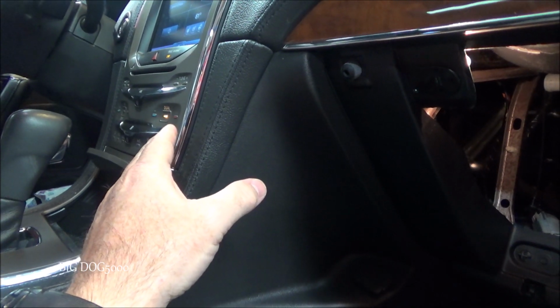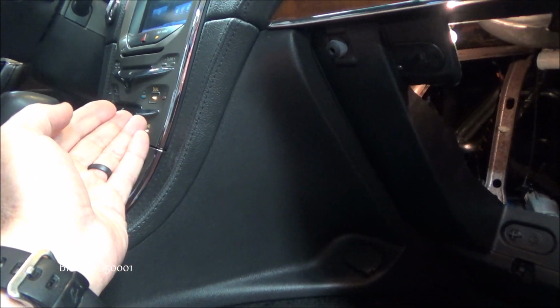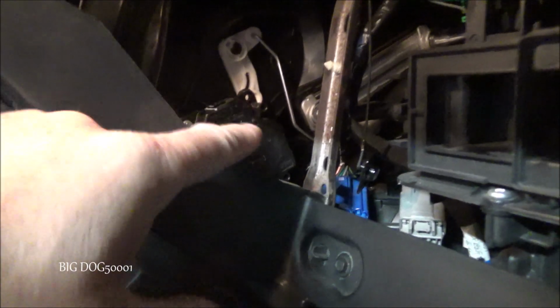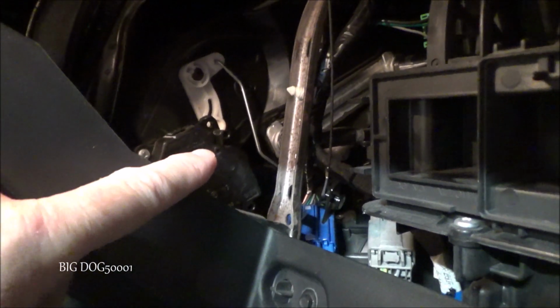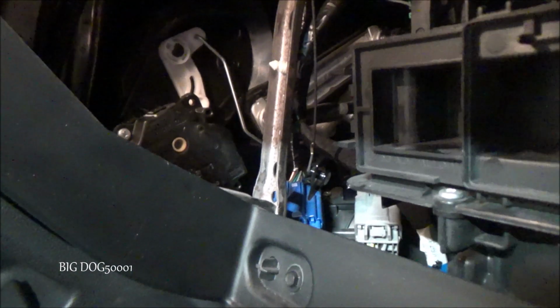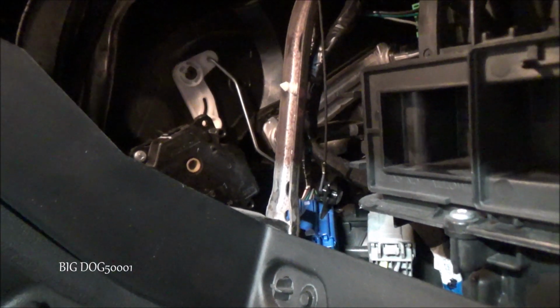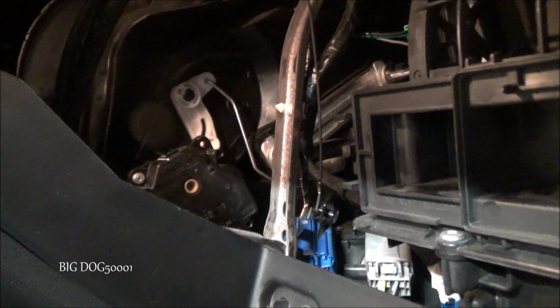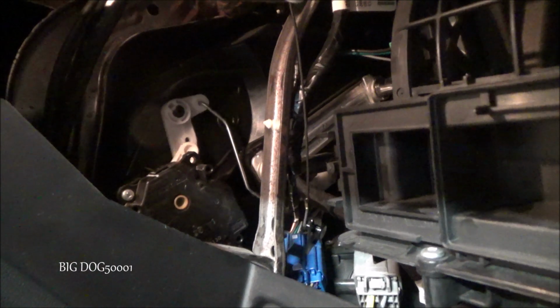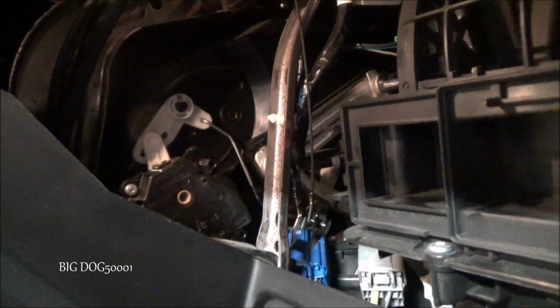You can move actuators just like you could on a scan tool, but we can do it right from our climate control unit, because I can control all these with a scan tool also. And so that's what I did with our blend door motor or actuator here. I just changed the temperature, so I'm gonna change it again. It was on cool, we're gonna go to hot, and we'll watch for movement on that door. And there we go, it just moved right there.